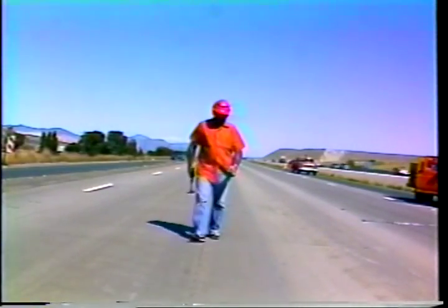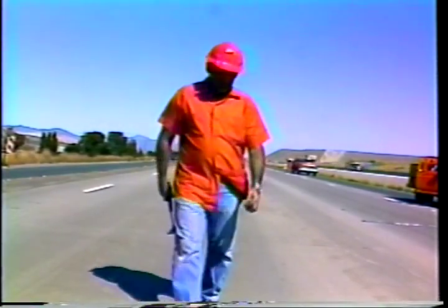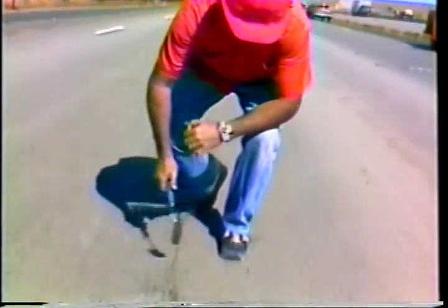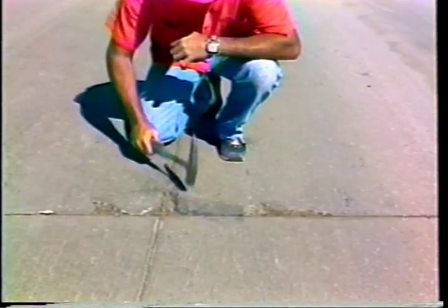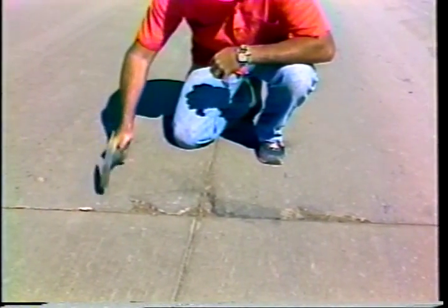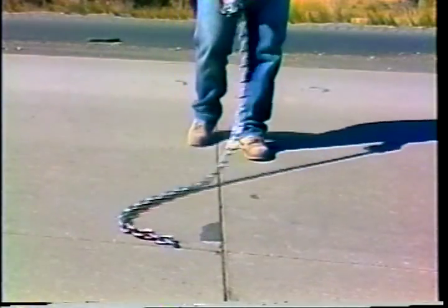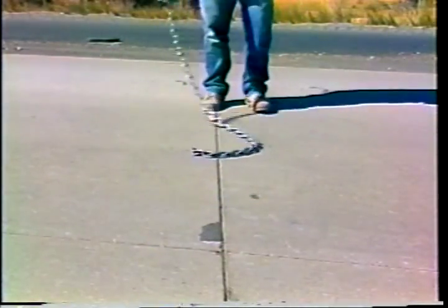Because pavement deterioration is progressive, however, the exact boundaries are not established until the time of the repair. In many cases, the extent of deterioration will not be visible. Delaminations may lie just below the pavement surface. So the exact boundaries are determined by sounding the pavement with a steel rod or a lightweight hammer, or by dragging a steel chain across the surface.